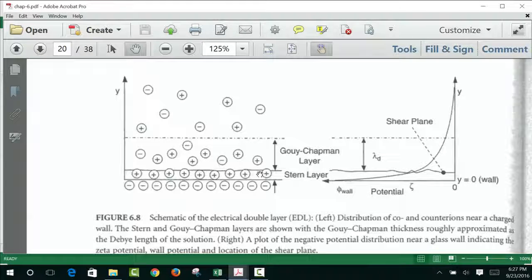Because this thing is not a meter. This thing is like 1 millimeter, 2 millimeter. I mean, the channel will be long, right? The height is small. But we are putting the electric field across the length of the pipe. Right? So you're talking about, say, 10 millimeter or something. So you put 100 volt and it's like 100 over 100. So you get 10,000 volt per meter, or 10 kilovolts per meter, basically.